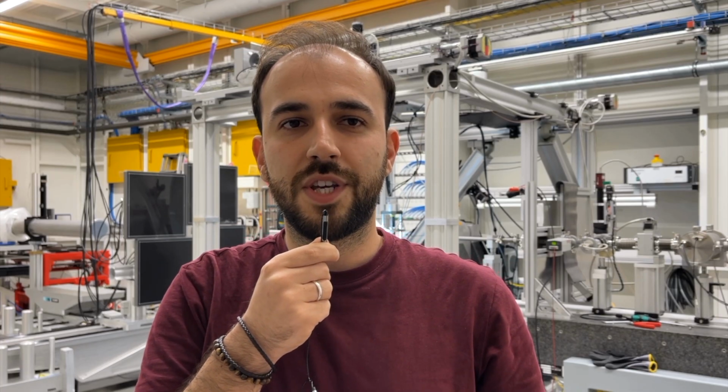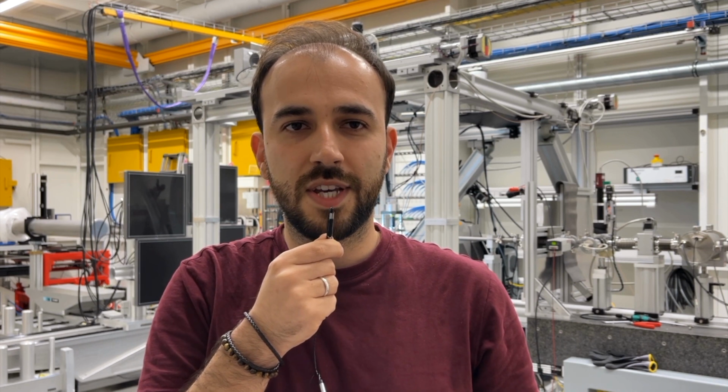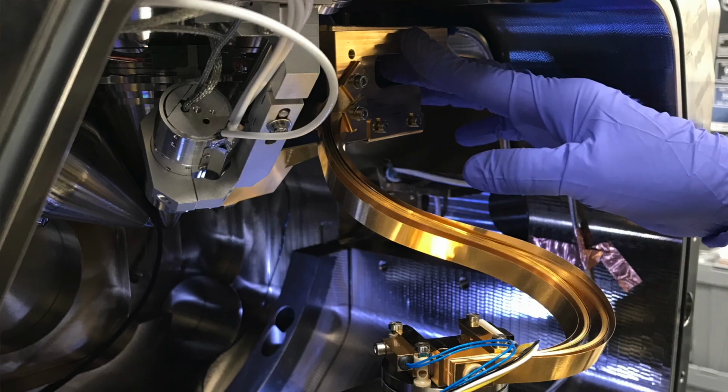During my project, we carried out several proton irradiation experiments over a range of doses, from very low dose regimes, including differing dose rate irradiations, to explore this effect. The resulting damaged structures were investigated using state-of-the-art machines including STEM, PFIB with cryostage, APT, nanoindentation, and a novel microbeam transmission synchrotron XRD technique. All the irradiated material characterizations during my project were carried out from the cross-section of the samples, where the entire proton irradiation depth-dependent dose profile can be investigated.